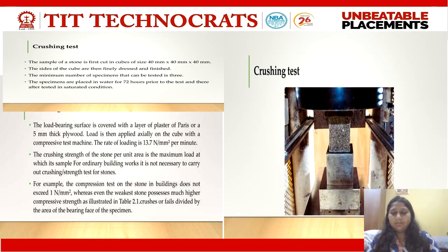A point would come after starting the machine where I would observe crushing of my stone or cracks in my stone. That is the important point. Then I'll stop my machine. I'll get the maximum load taken by the stone, beyond which it is breaking, and that load is known as the crushing load.